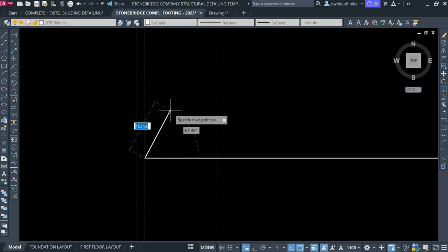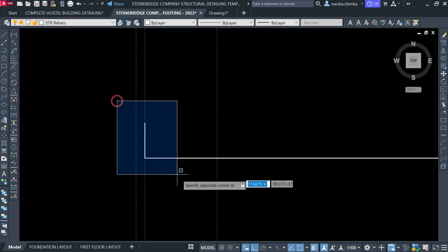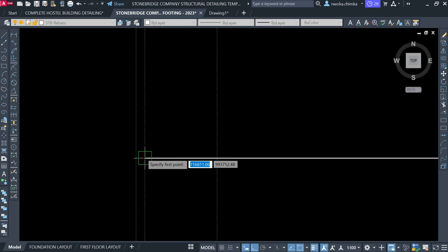Now a slab used to have a bent up bar, which bends up back into the slab from the beam. So this first distance here is always 100 in every slab, always 100. Sorry, let me go back right now. So I'll type L, enter, and type 100 here.